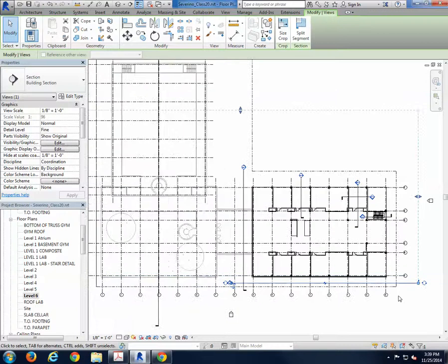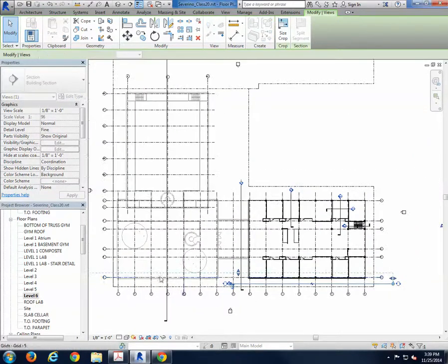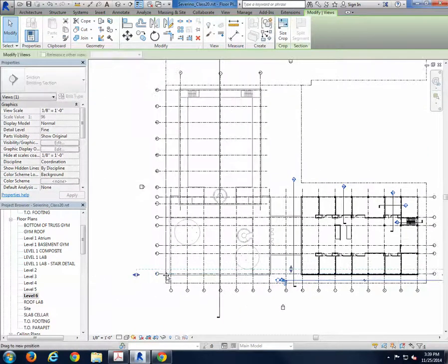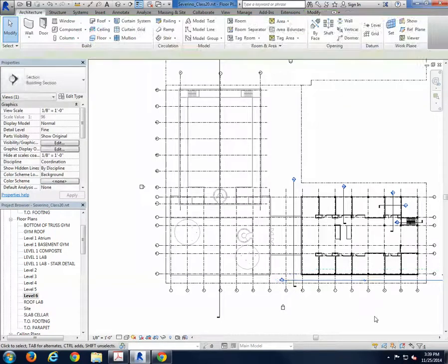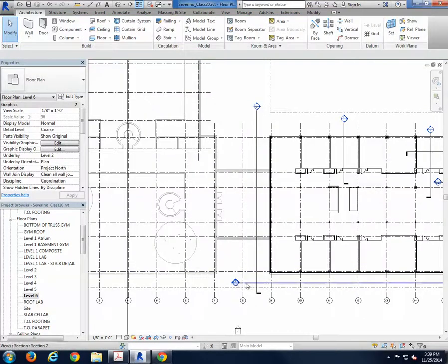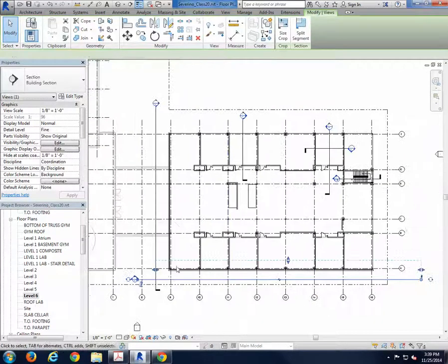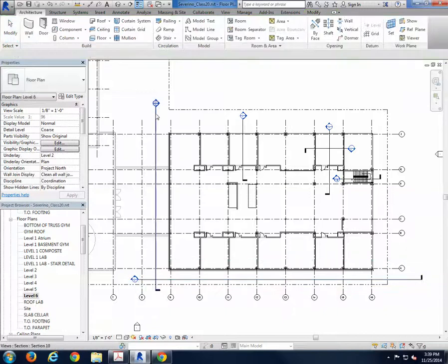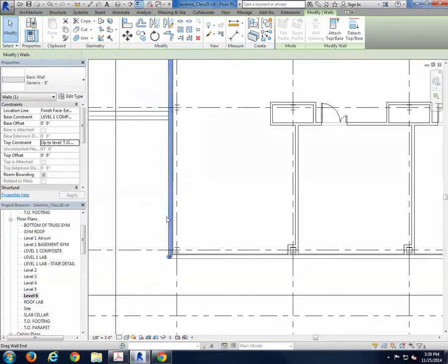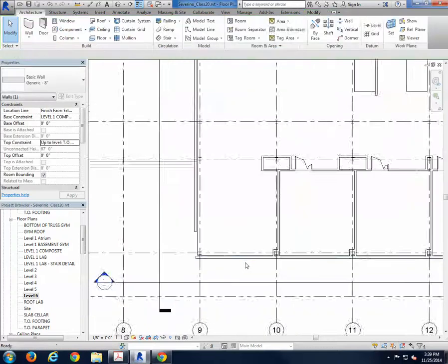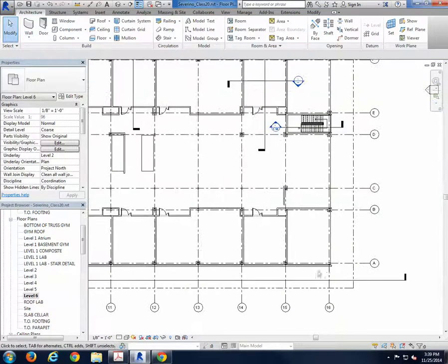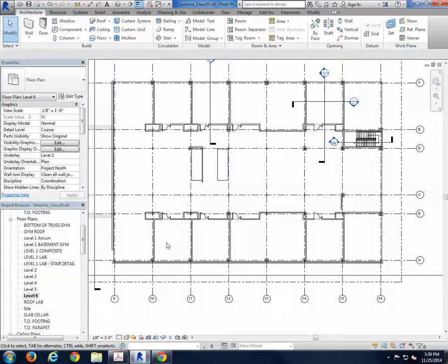Don't change any section that you have made previously, because you're actually changing how the section looks, so you're changing your sheet. Okay, so again, this section is looking at this facade, this section is looking at this other facade. I'm going to select this facade and move it outwards so it's independent, and we'll see how we treat these things.